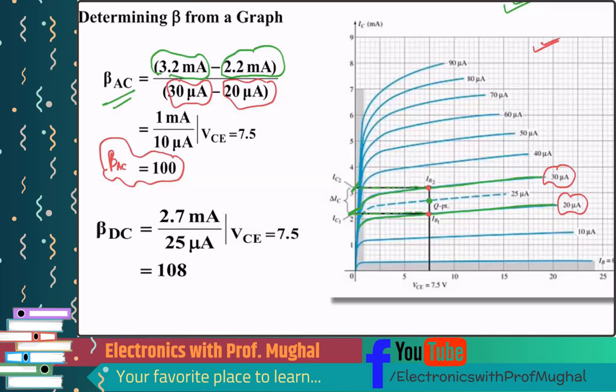And if you draw a straight line like this, it gets you a VCE, and VCE, I told you, is the output voltage. If you were going to calculate the beta DC, it's just simple IC over IB. So if I delete that, you don't have to draw the lines in that case. You only look for these values here. This was the Q point given in the question, so you just draw a straight line like this. It looks like 2.5 something, so it was 2.7 actually.